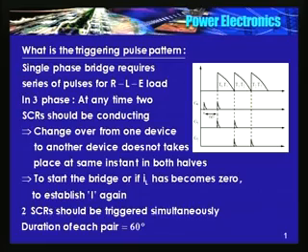In a single phase case, we found that if the load is of RLE type, current may become discontinuous. You have triggered the bridge T1 and T2 in the positive half, they started carrying the current.